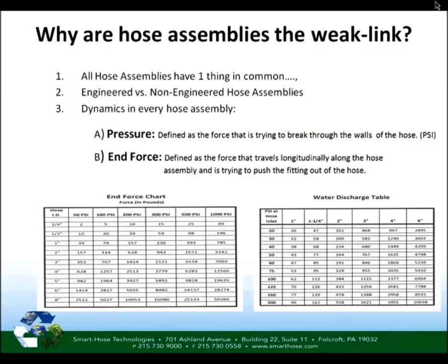Also, the construction of industrial hose can vary greatly. The outside diameter of the hose can fluctuate, which can affect the ferrule size and the crimp spec. The components are designed to work with a wide variety of industrial hoses, and the outside diameter of industrial hoses can vary from batch to batch. This in and of itself can create an inherent weakness in the hose assembly.